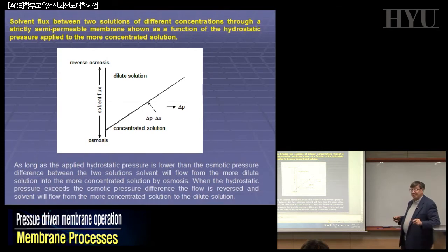The same problem can exist with temperature. In reverse osmosis, it is also present but negligible, but in membrane distillation you don't have a big problem with concentration, but you have a big problem with temperature. Exactly the same kind of phenomena. If the temperature difference across the system is not enough, you can have flux on the other side, and thus you don't operate your separation. So these have nothing to do with the membrane performance, they have to do with the system, with the flow dynamics of the system.